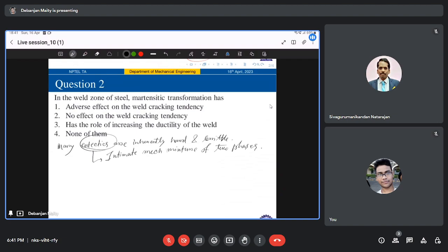Another option, of course, is to attempt to modify the structure of a lamellar eutectic, and how that can be done is you can do some long time soaking at elevated temperatures, and basically second phase particles will form in a spherical structure within the matrix of the first phase. The driving force for this is the reduction of interface energy, right? And the process is called spheroidization. So you can do some spheroidization and modify the eutectic structure, do some heat treatment to solve this problem, right?